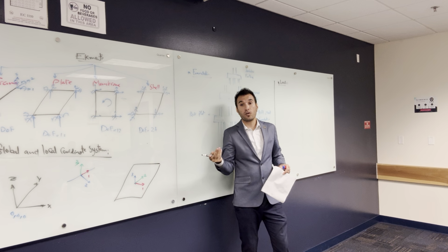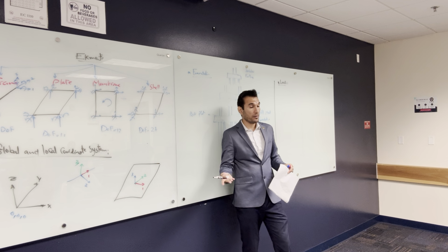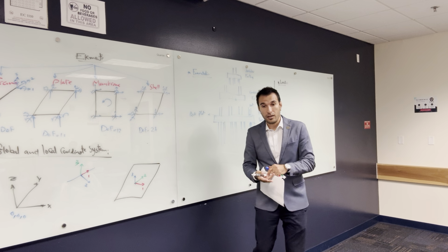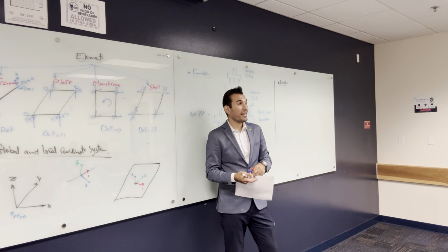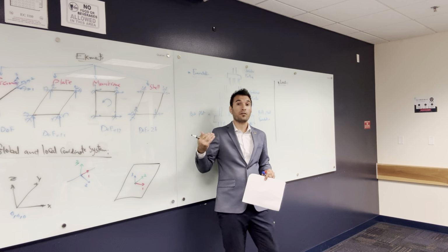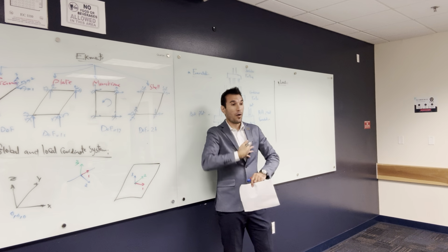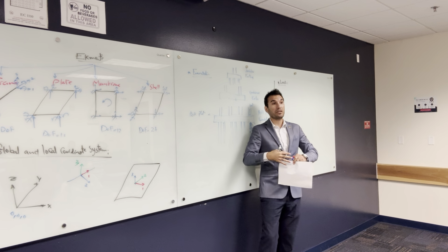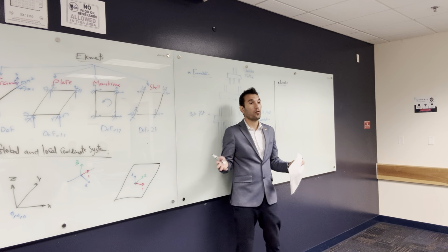There is a load case that's called live load. Each structure based on its use has different live loads. Like residential building is different than commercial building, is different than universities, because there's lots of people in this room. So the live load definitely is much bigger. That counts for our load, the chairs, the furniture, whatever happens here. And we calculate based on the maximum, like this room is really full.